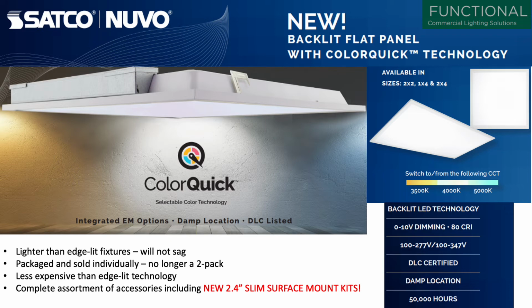Why? Because most of the ceilings are suspended and these fit right in, or lay in, to the suspended ceiling. In the model that you see in front of us, this is a flat panel that features Color Quick with 3 different color temperatures that can be adjusted by moving the switch. It has 2 voltage packages, 100 through 277 and 100 through 347 for those applications that may be in Canada. It's DLC certified, which makes it available for utility rebates, and is 50,000 hours.